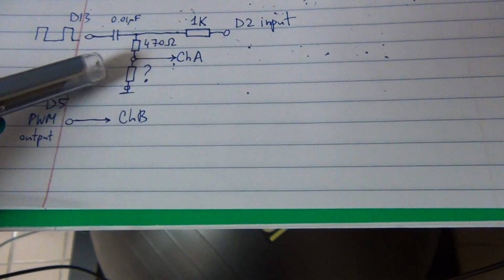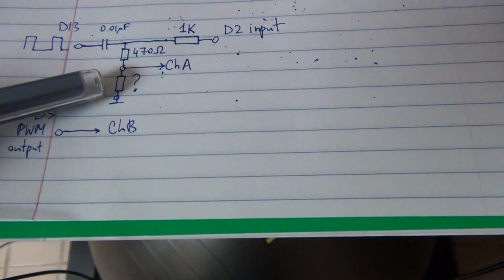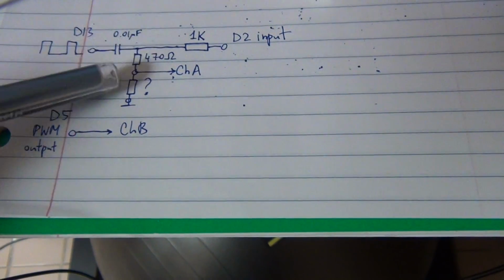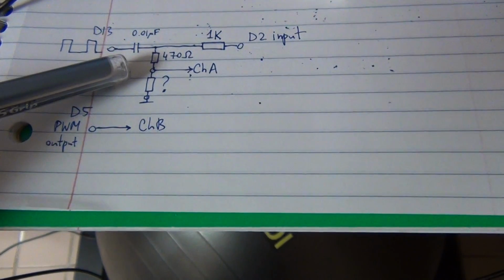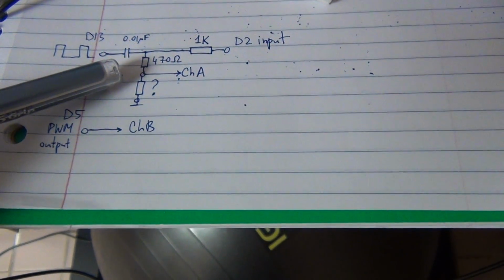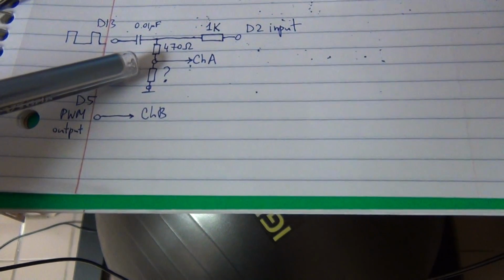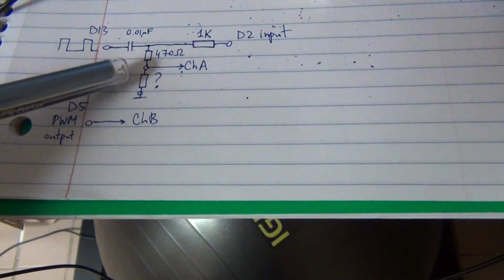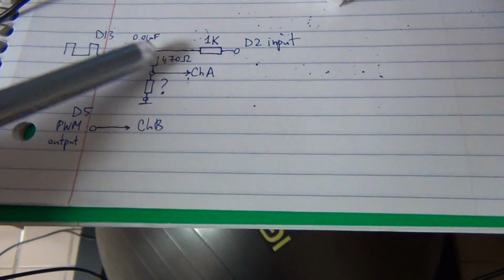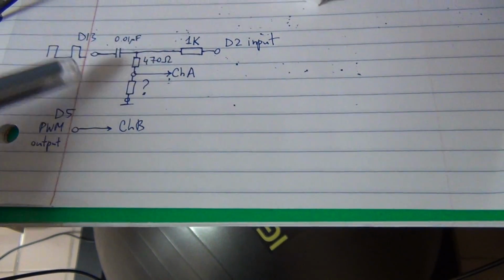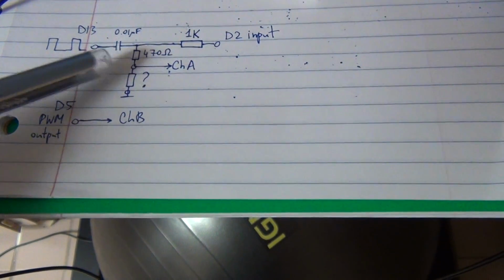Now we will have the resistor under test decoupled from the capacitor with a 470 ohm resistor. Why is that? People really like to put test lights over here, and we don't want pin D13 loaded too much if this is shorted or 12 volts are applied.